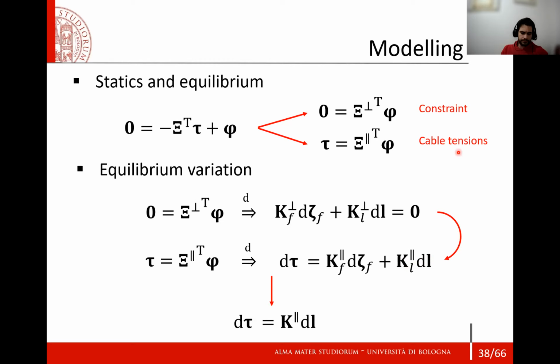If the cable length changes quasi-statically, the differential analysis of the static constraint establishes the causes of the free coordinate variation due to cable length variation. In addition, we may also determine how cable static tensions are affected by cable length changes, which was our objective to start with.